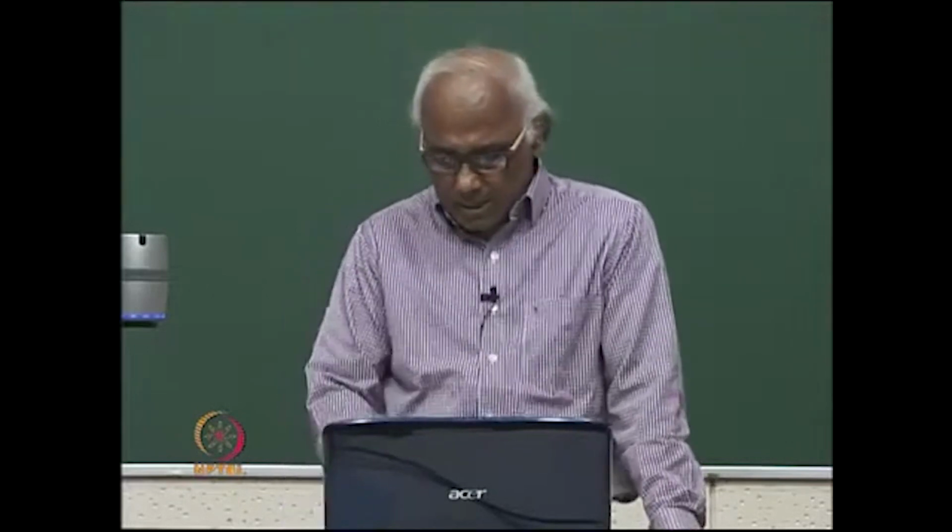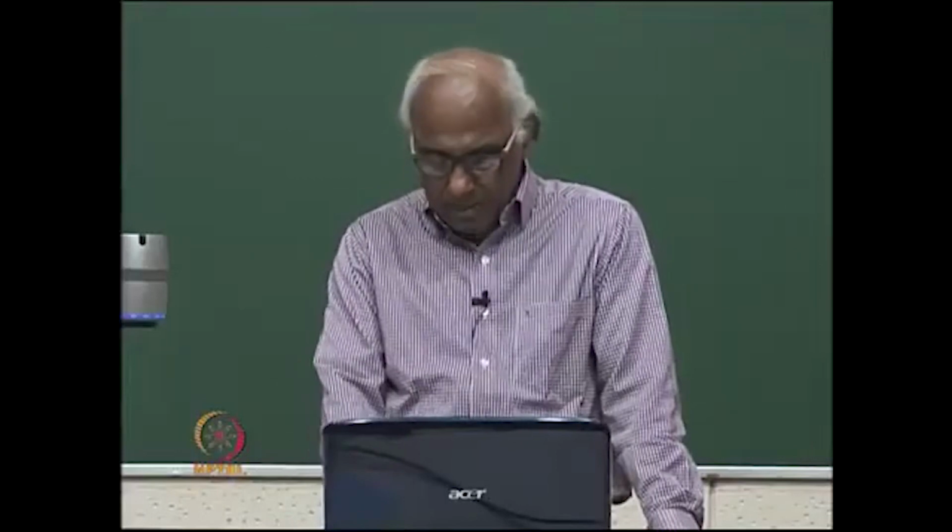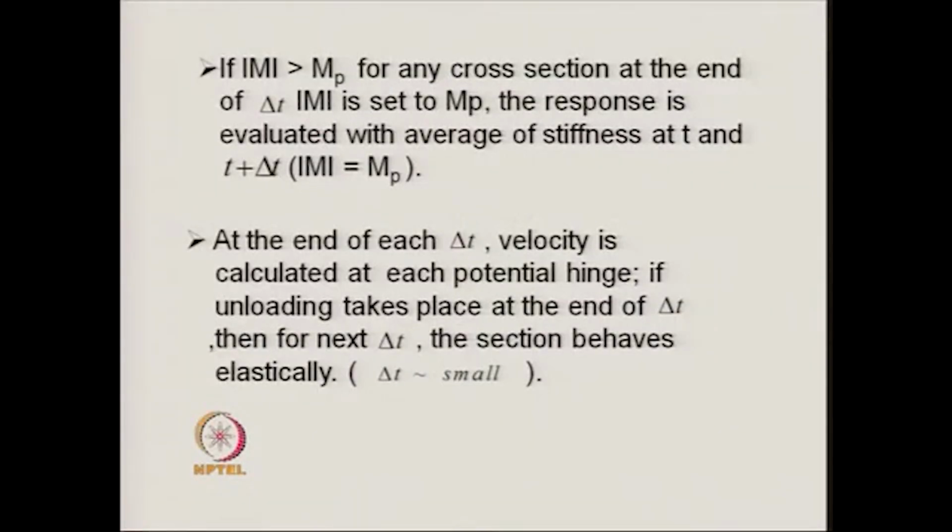And when we get that incremental displacement, then we add the incremental moment to the previous moment and see whether other cross sections are yielding or not. If the M which is computed at the end of any calculation becomes equal to or greater than the plastic moment,